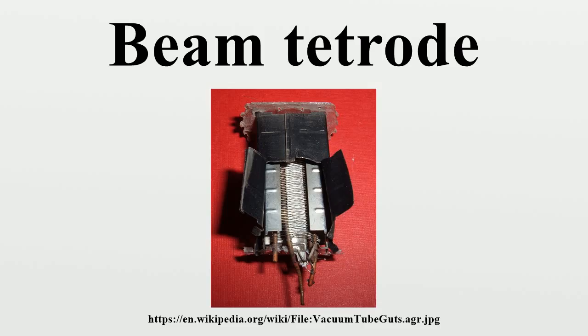The design is today known as the beam tetrode, but historically was also known as a kinkless tetrode, since it is a four-electrode device without the negative resistance kink in the anode current versus anode voltage characteristic curves of a true tetrode. Some authorities, notably outside the United Kingdom, argue that the beam plates constitute a fifth electrode.